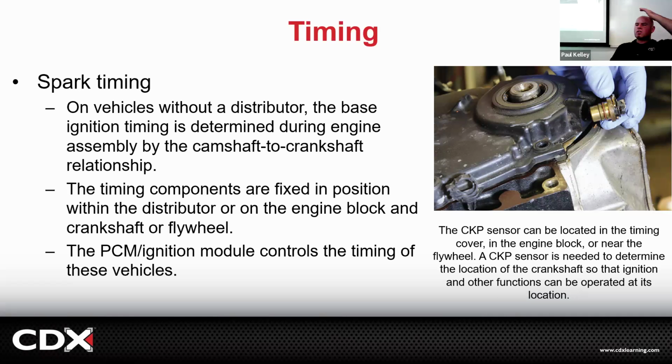But have you guys ever heard of taking a car to the tuner, bone stock, tuning it and gaining 10 or 20 or 50 horsepower? Because that tuner will go through and actually break into the ECM and advance your timing even more. Now, if they over advance it, you'll damage the engine. But usually the manufacturer leaves a little margin where you could get a little more power out of it. Back in the day, they left a big old margin. You'd get a bunch more power out of it. But now they're taking most of that because they want the power, they want the fuel economy, and they want the better emissions, right? So on a non-distributor car, timing is all controlled with the computer, with the PCM.